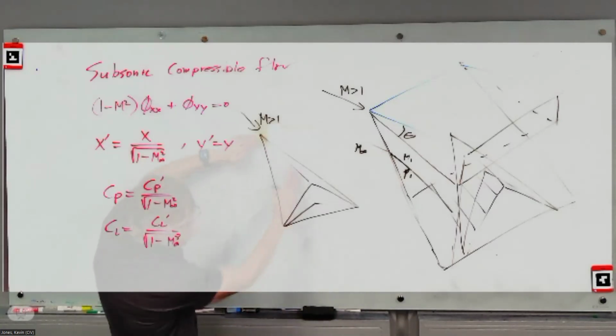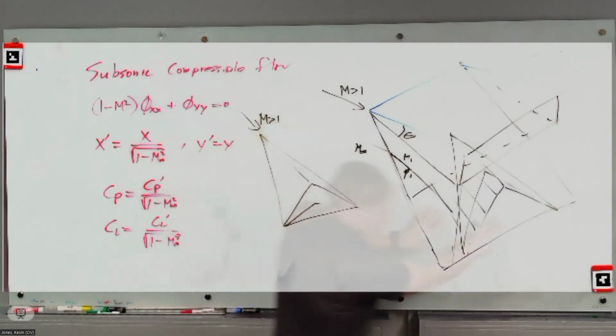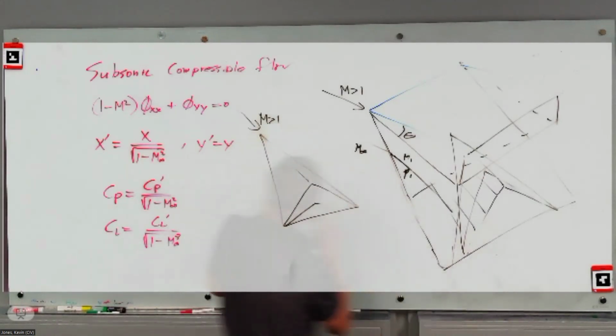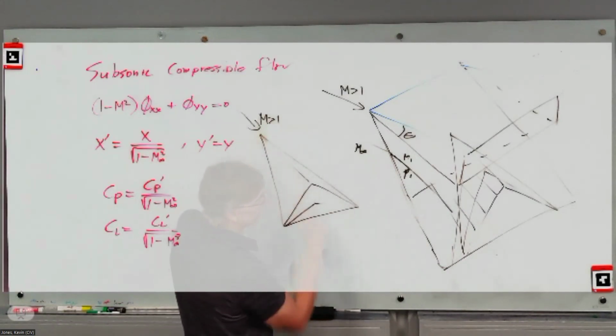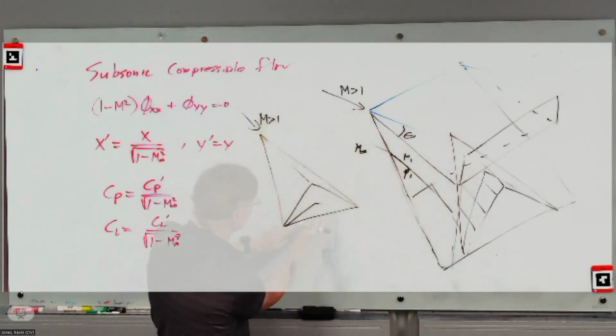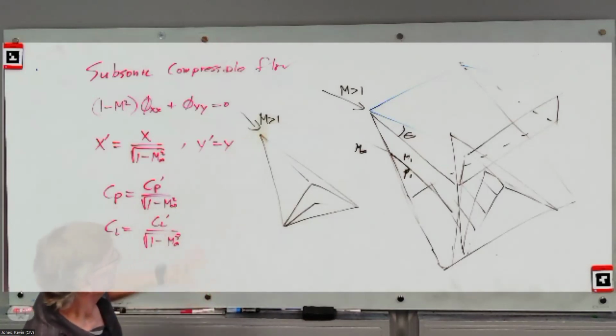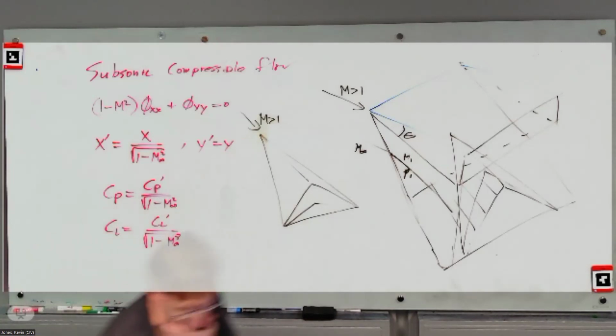If I change the angle of attack of this, that shock is no longer going to be where I thought it was. I developed the shape by knowing what the flow looked like. But as soon as I change the angle of attack, normally that would mean that the shock angle would change and have to come with the body. So this body, suddenly the shock is going to either get squished up the side or get thrown out. And then the flow properties are all going to be variable in there. It becomes a messier thing to solve. Anyway, that was all the rage for a while.